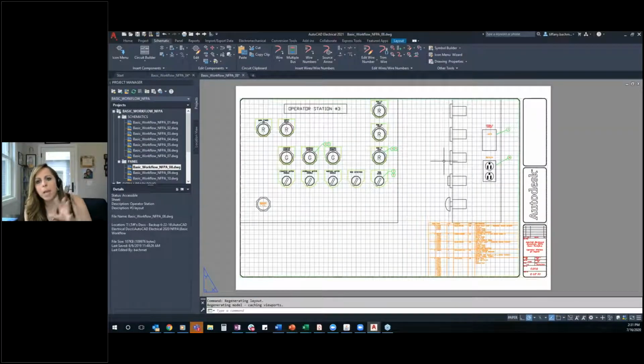So really your paper space, and by the way, everybody, whether you agree or disagree with me on how it's drawn or being able to use scales or not, setting up paper space will allow you to do a multi-sheet plot far cleaner and easier than trying to do that out of model space. So you will have a much better success rate of being able to send all of your drawings to a plotter or even to a PDF for plotting. It will all have the page setups in a much better format for you.